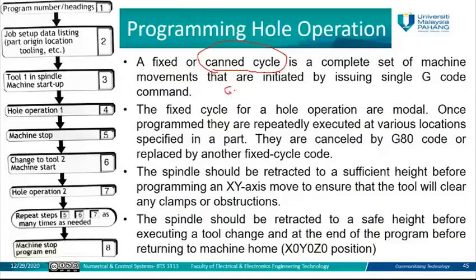You are going to use this code directly in the G code that you develop, and it will be used there to create the holes. It's like a complete subprogram. We call it a canned cycle.